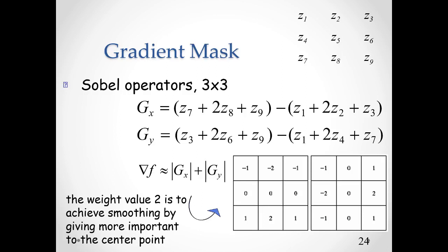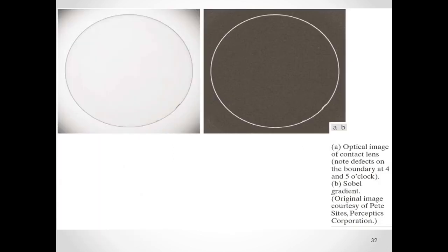So if you see the isolated point, here the response is much stronger for second order derivative than the first order derivative. Hence we can say the second order derivative enhances the fine detail, including the noise in an image, compared to the first order derivative. If we consider the gray level step, the response of first order derivative and second order derivative are the same. So in conclusion, we can say that the first order derivative generally produces thicker edges in an image.